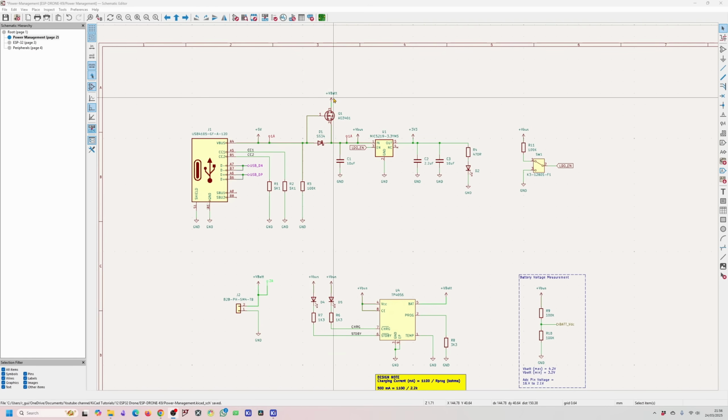So we've already discussed that different signals have different electrical requirements, and net classes allow you to communicate that effectively with a built-in tool in KiCAD and various other ECAD software that you might use. In KiCAD, with net classes, you can define a set of rules that, when you go onto the PCB side, control the thickness of tracks and everything. So if you do a DRC check afterwards, it flags up an error if you are not meeting those requirements.